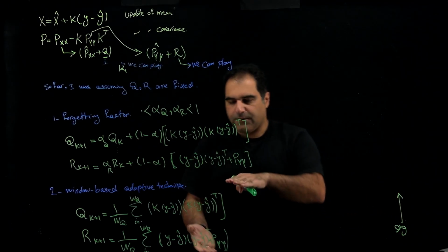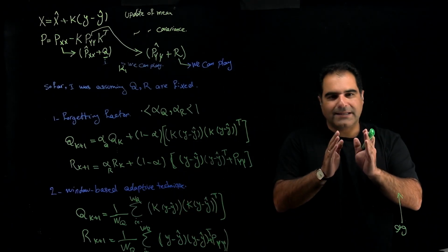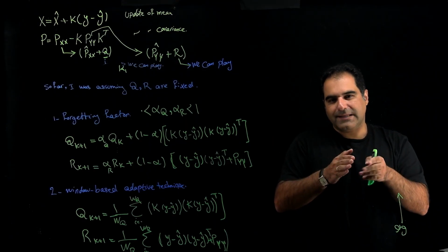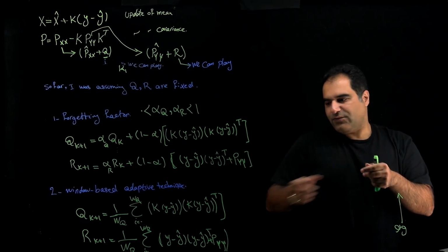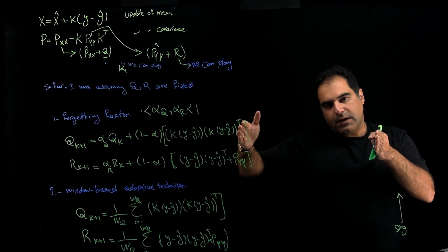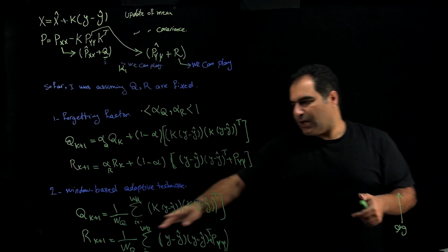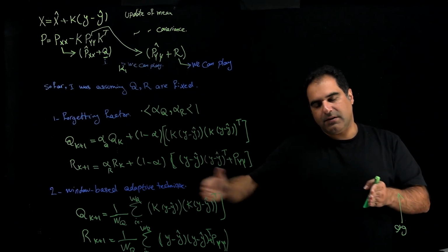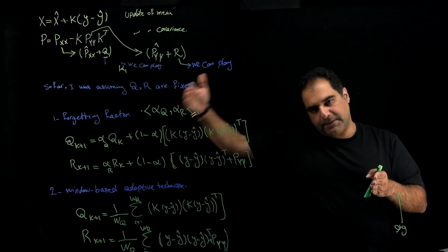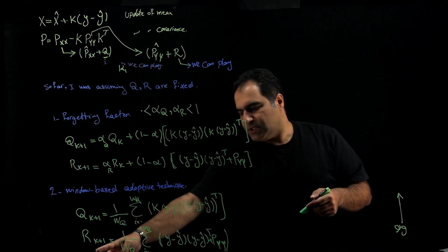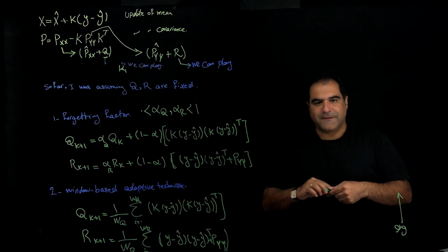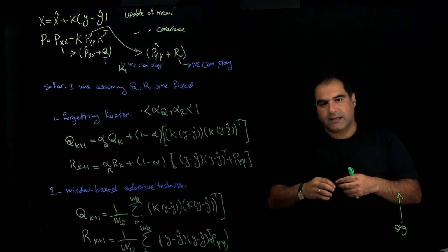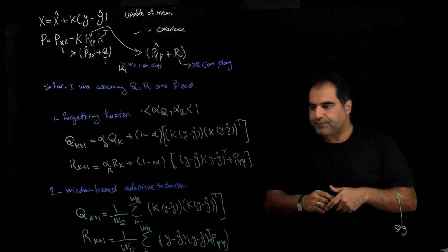It means for this technique, you choose a window and you look at the predictions and the innovation in a specific window, and in each iteration, you take the history of the signal up to a specific time step and calculate Q and R for that time step based on the previous prediction and sensor data and considering the window you choose.